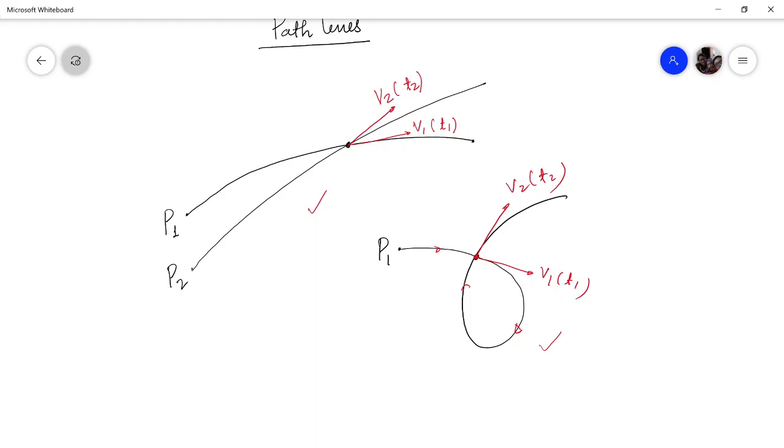What do we do in practice, in the lab? Let us consider that I want to analyze the flow field in this particular pipe, and water is flowing. I will drop some neutrally buoyant particles. Neutrally buoyant means the density of the particles and the fluid are the same, so wherever you drop these particles, they will stay there.